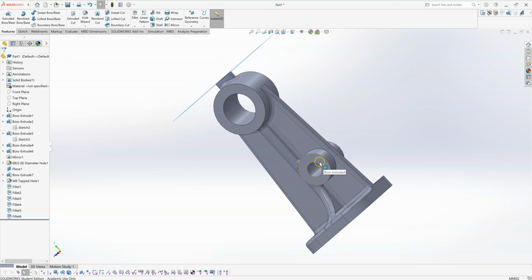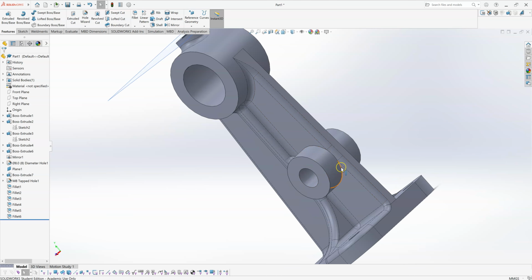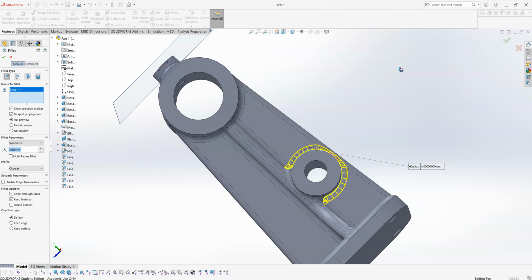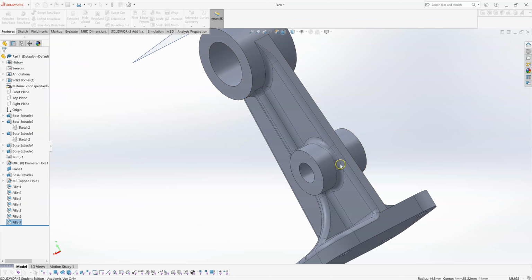Okay, these cylindrical faces I think remain flat. So this whole part would be a casting, for example, and then those faces are probably machined flat afterwards. Actually, I've missed these internal corners here as well. Do a fillet on those as well. Radius 3 again, all around there like that. Now, I probably should have done that before I rounded over this external corner here.